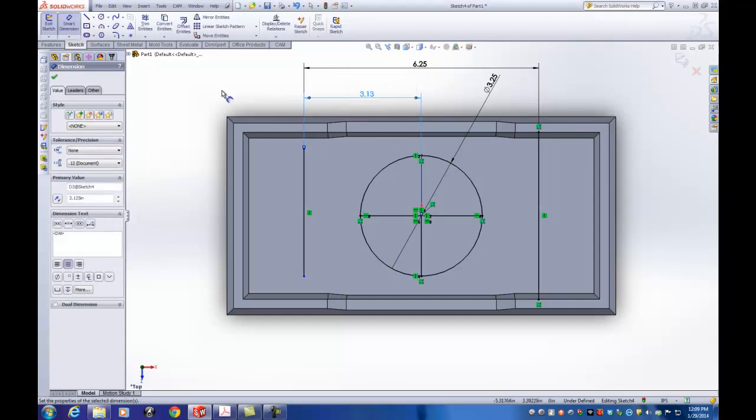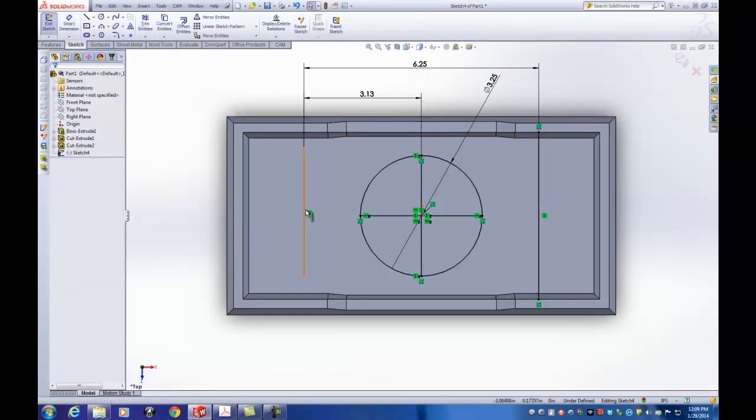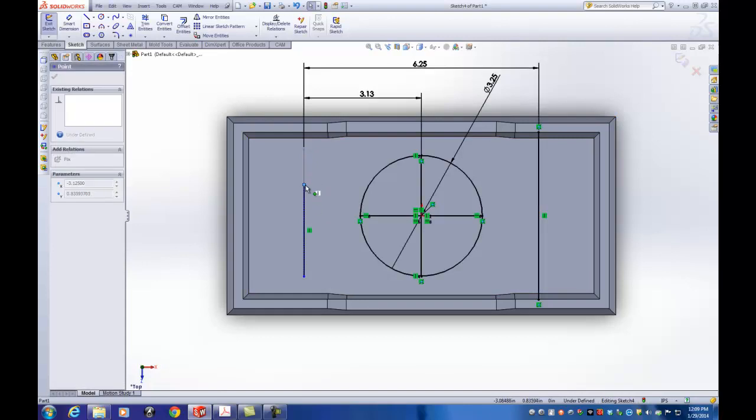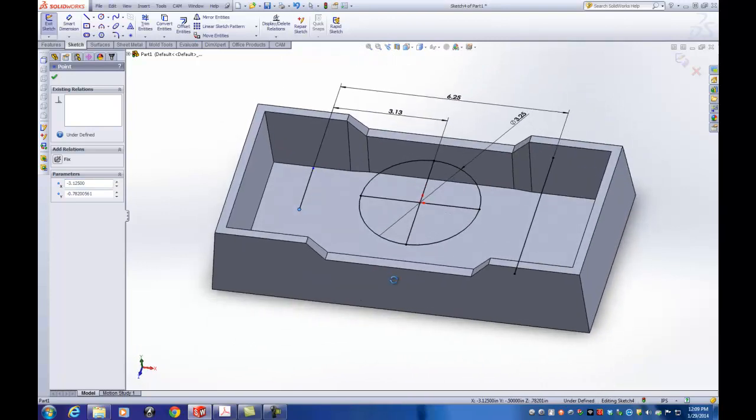But I did this, this rib line here is short. It doesn't actually touch on the corners. This one here I connected with a coincident constraint as it connects on those edges. That's really all you need to be able to create a grid of ribs.